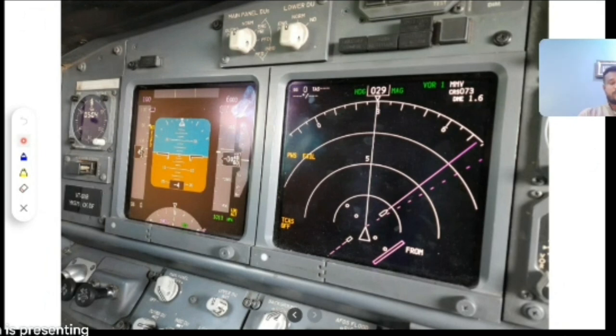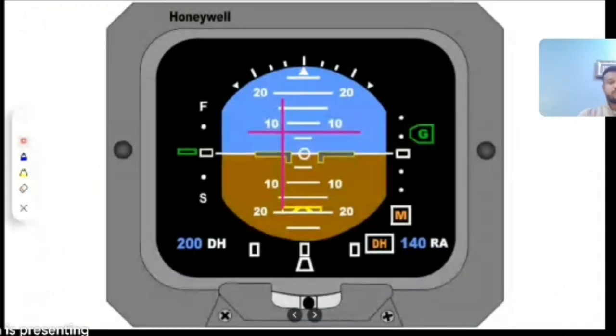Okay. So what is this indicating, guys, these two lines? Suppose you're sitting in this aircraft and you saw this kind of indication. What does it indicate? The aircraft is left of the runway, and a little bit off the runway center line, and a little bit above, right? Yes, and it is